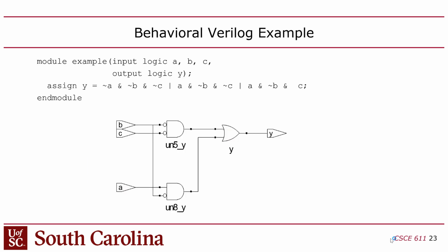Okay, so first that was simulation. Synthesis looks like this, where you have the logic here, and it will actually convert it to a gate level netlist or a gate level schematic for you. And the tool will actually do this. You can take your code and launch a tool called the RTL viewer in Quartus, and it'll show you the gate, and this actually came right out of Quartus.